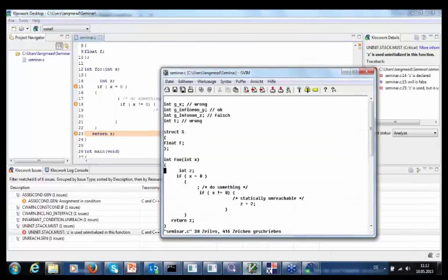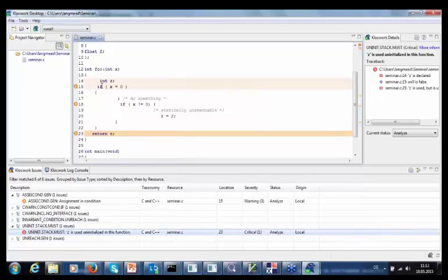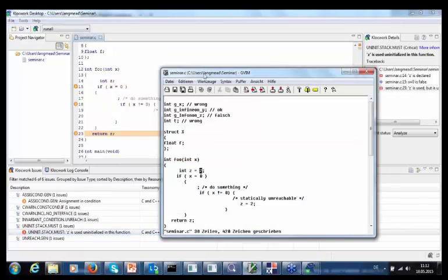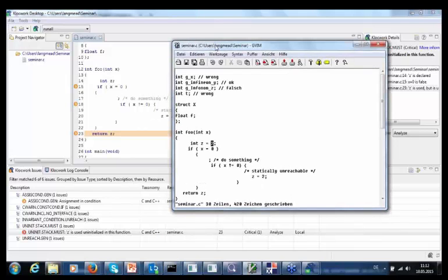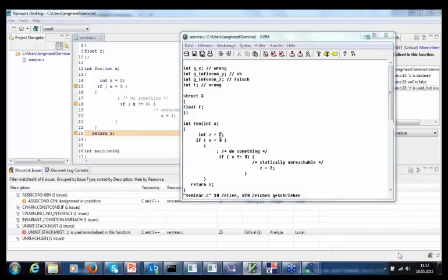So now as a developer, I can go through, for example, and see that I have a possible uninitialized variable, which the tool and our solution highlights here, which is critical for an embedded system. We could then fix that here, and as soon as I make the fix in my editor, the analysis is started in the background automatically. So you can see, hopefully on the bottom right-hand corner, the analysis is restarting because I've synchronized with the analysis platform. In this way, we can go through all our defects and fix them before the code is checked in.